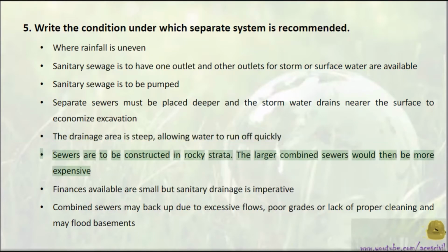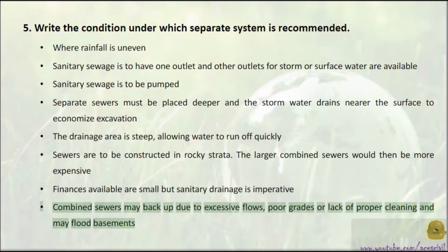Sewers are to be constructed in rocky strata. The larger combined sewers would then be more expensive. Finances available are small, but sanitary drainage is imperative. Combined sewers may back up due to excessive flows, poor grades or lack of proper cleaning, and may flood basements.